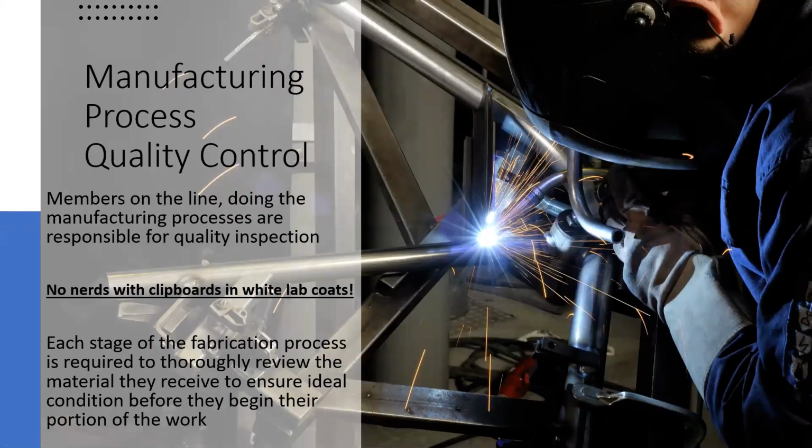So you've got your coatings, and really you want to make sure, as we talked about in the lean process, that you're creating something consistent all the time. So you have a quality control piece. This is very common in any manufacturing facility, but especially from a lean perspective, you want to practice quality at the source. What that means is you don't want to cut something out on a laser cutter and find out there's an issue when you're assembling it and getting ready to ship it.